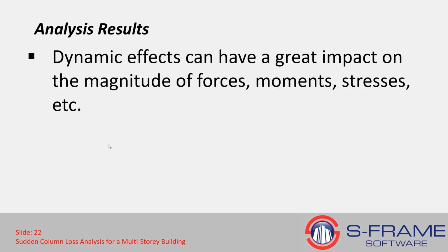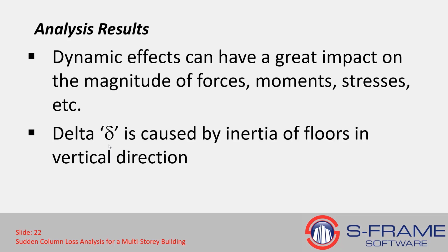The dynamic effects clearly have a great impact on the magnitude of forces, moments, stresses, and deflections. If we were to very slowly load this floor, the dynamic effects would not be as noticeable, and without any oscillation overshooting, the structure would settle into the equilibrium position as we run a static analysis. So the delta I showed in the last slide is caused by this inertia on the floor in the vertical z direction.